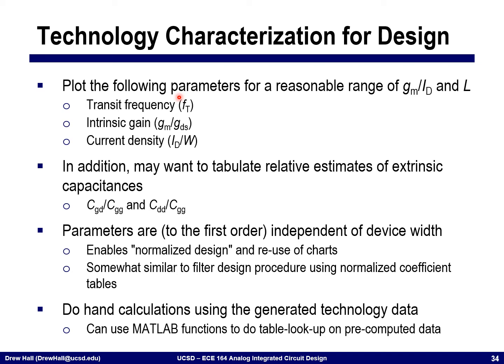I can literally make these charts once, print them out, or even incorporate them into my optimization loop, in things like MATLAB or Excel, in order to read these charts and size the devices as I see fit. If you've ever done filter design, this is quite similar to using coefficient tables to calculate all of the different components of the filters.